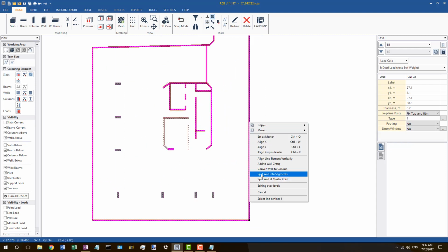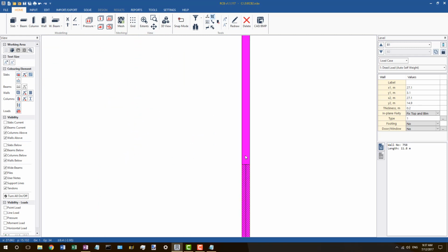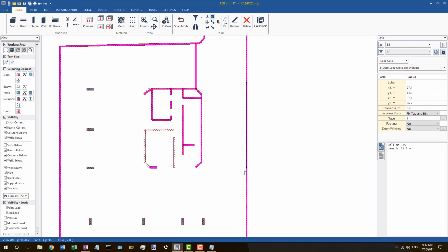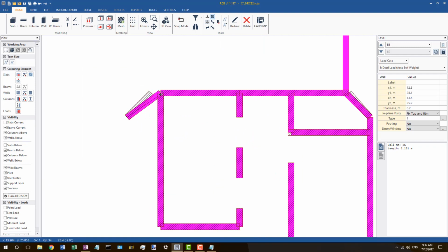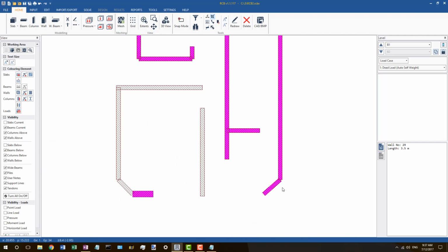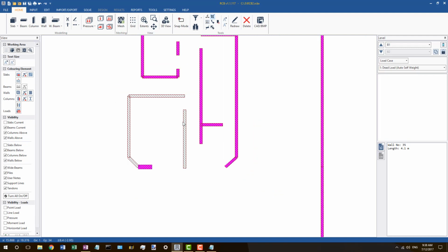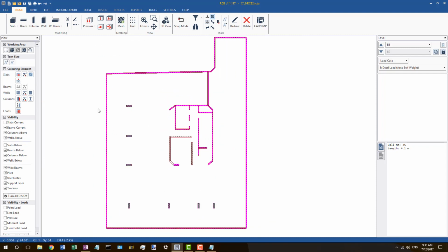This one was 3 segments. So again, important thing to note, that starting and stopping point is at the same location, so there's no slight offset, so there'll be no meshing errors there. We'll just manually go through and fix up these walls in the lift and stair shaft just so that they match above and below, so that there are no meshing errors there. This all looks okay, and we'll just pull this back so the center line touches correctly. So the walls now are done, columns are looking good.